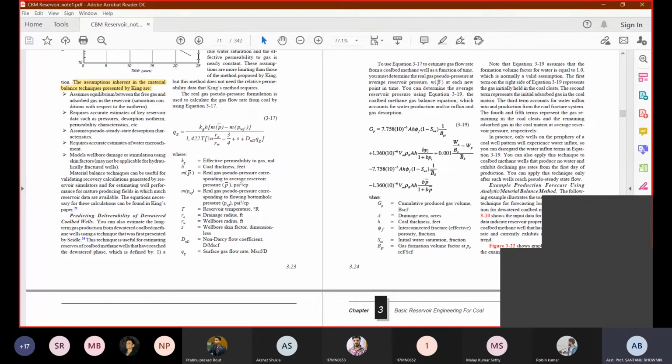whatever fractures intercept the excavation, in this case the borehole, you will find that if there is any other rock strata which is very strong, then the water inside cannot come out into the borehole. But if it is very well connected, like a coal bed methane reservoir, like a coal mine situation, you know that coal is very prone to fractures. So water connectivity will be there, and the more you drill, all the water will come into the borehole and be accommodated in that borehole. So you have to take out the water before you do any further drilling.